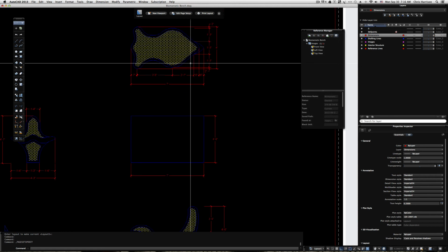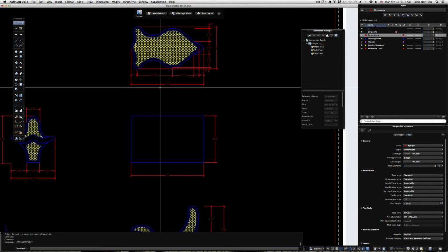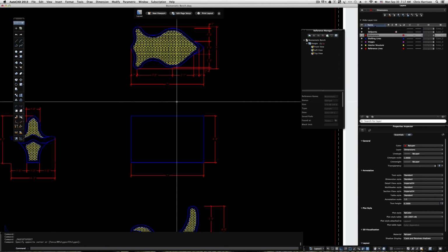So in LDI 2007, the red lines are very thin, where the white line is the thickest line. And we can kind of see that through this track. You see the typical color spectrum in CAD is going to be red, yellow, green, cyan, blue, magenta, and white. The LDI system starts from red being the thinnest and works its way up to white being the thickest line. So when you draw, you don't have to think about thickness as long as you know that red is the thinnest line and white is the thickest. It's already pre-programmed in. So when you plot or print, it will print with those thicknesses that correspond with the color. So that's what the pen settings are.